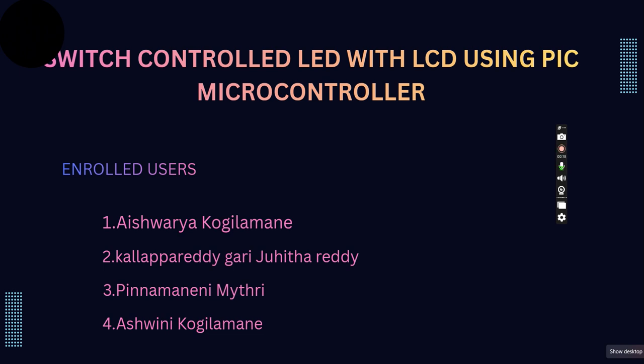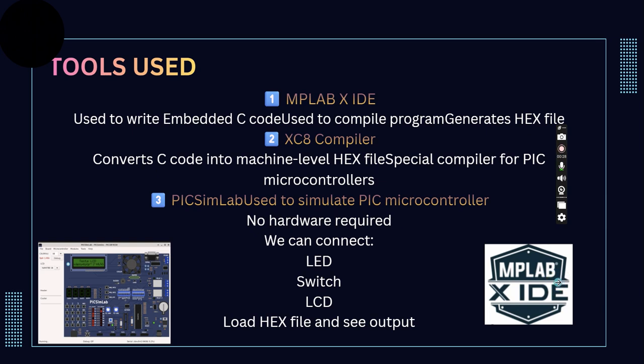Let's discuss tools used. MPLab X IDE. This software is used to write the embedded C program for the PIC 16F877A, and we compile it with the XC8 compiler and generate the hex file that will run inside the microcontroller. XC8 compiler converts the C code into machine code in hex format so that the PIC can understand and execute the instructions according to that.